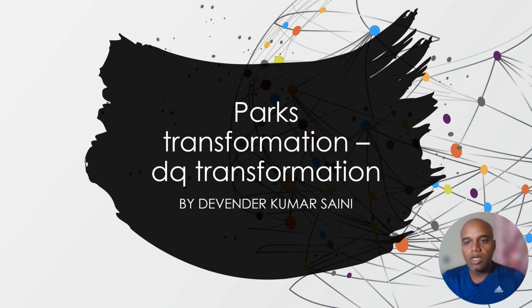Therefore, the Clark's transformation and the Park's transformation both serve this purpose, to convert my three-phase ABC reference frame, which is happening in my AC motor, first into the two-phase orthogonal reference frame.